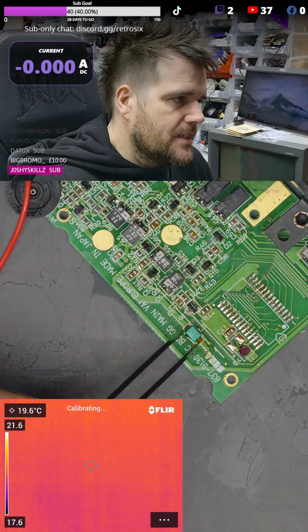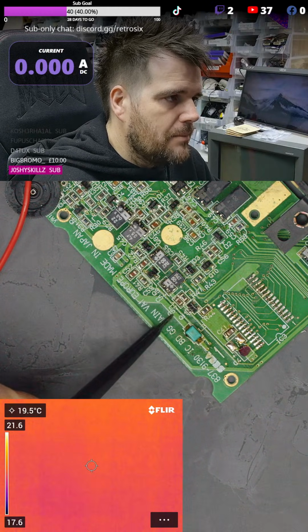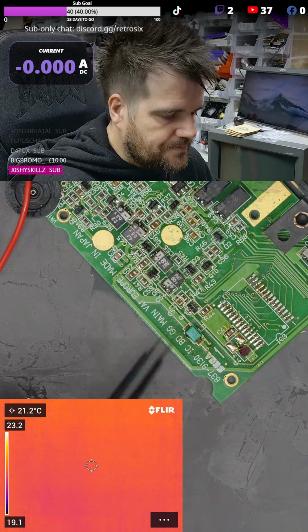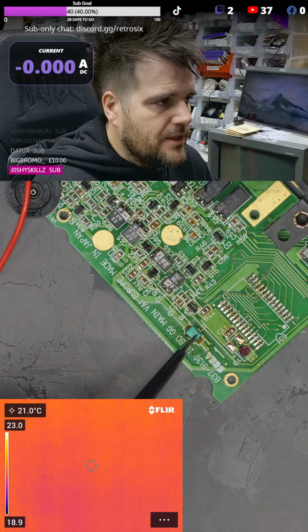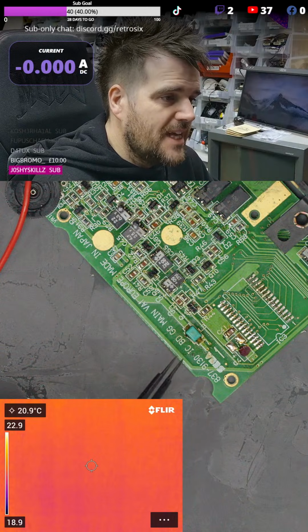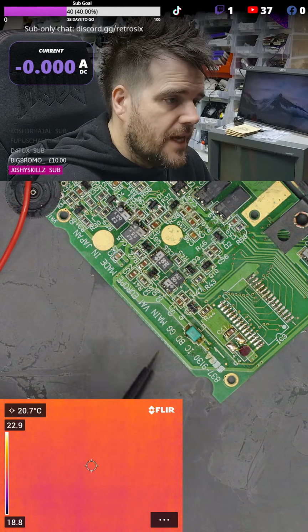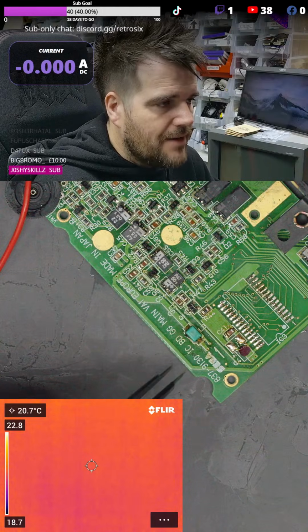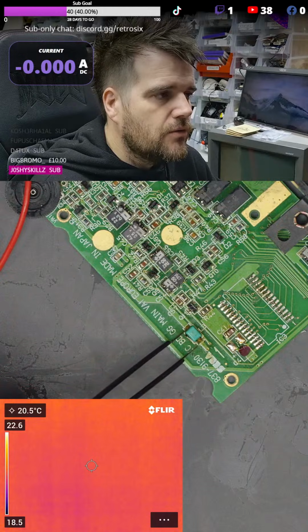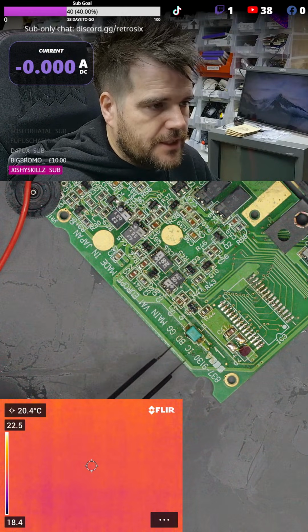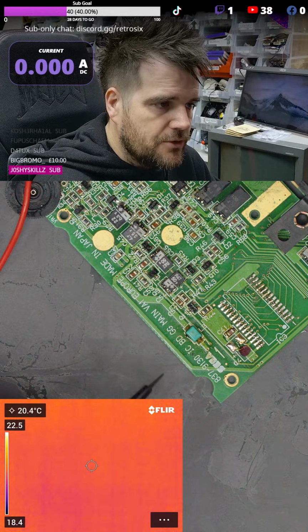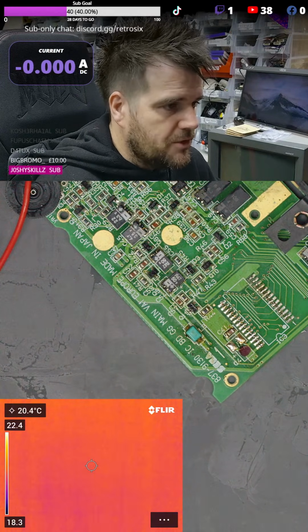What you have to understand is that there are parts of a circuit that power can pass through, that if there's too much current on them, like power circuits, they'll get warm. So it's not necessarily this inductor. One of the most common things is people see inductors and think they're faulty. Inductors are almost never, ever faulty. And they almost will never get hot if they're faulty. They just won't work. I've never known an inductor to short because they are effectively a short anyway. They're a coil of wire. They can't really ever get hot because they are faulty. So I have never once, in finding problems on a board, found an inductor that gets hot because the inductor's the problem. It just isn't a thing.